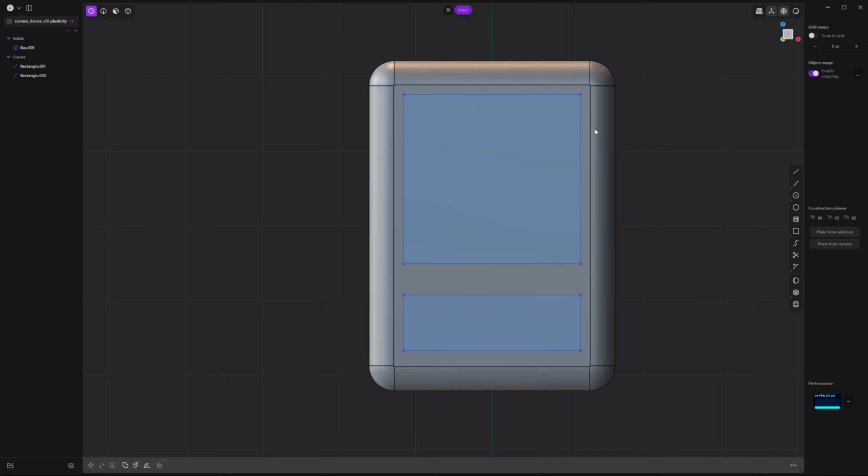All right, next thing, we're going to create that interesting X shape by adding additional points. So go over to Split Curve Edge at Point, and you're going to hover over the center of this curve and just drop in a point. Press Shift R to repeat that same tool and block it out in all the other sides. We're going to add a total of 3 points, so we have 1 down, and they're just going to be in the halfway marks of these as well. So press Shift R again, and we're going to drop these in the middle. And I'm just pressing Shift R every time I drop a point to repeat that command.